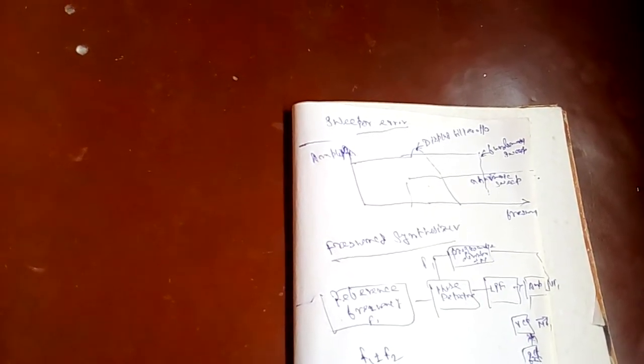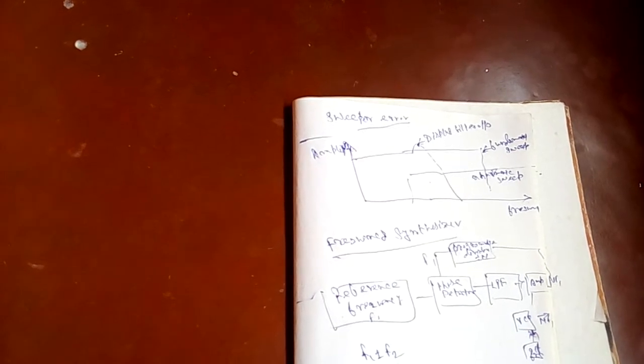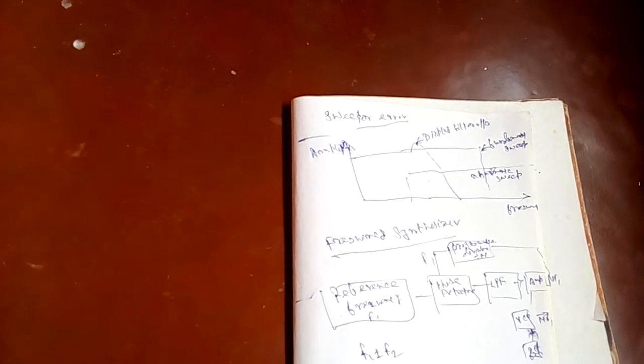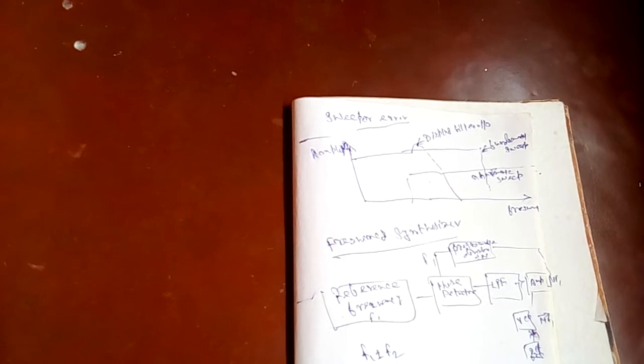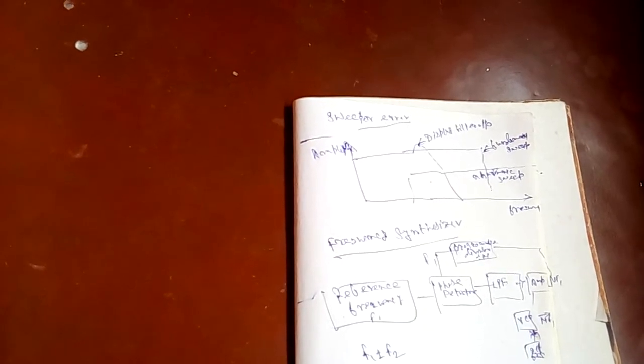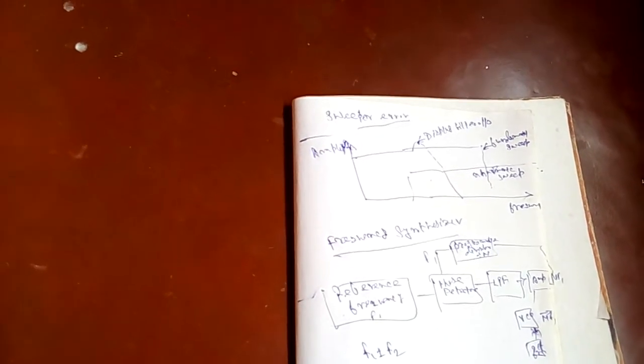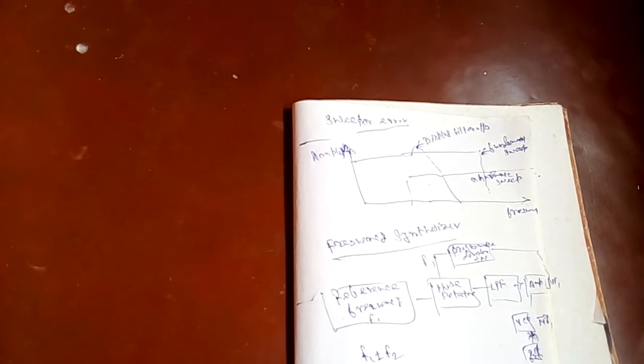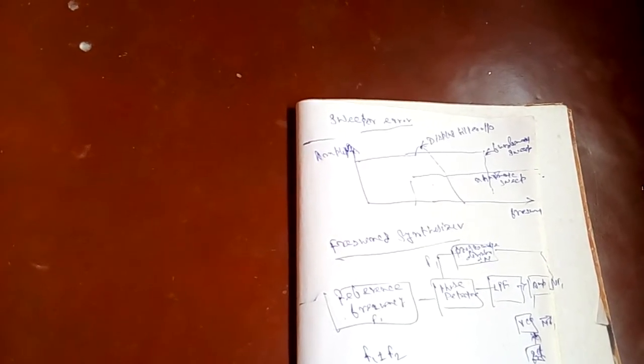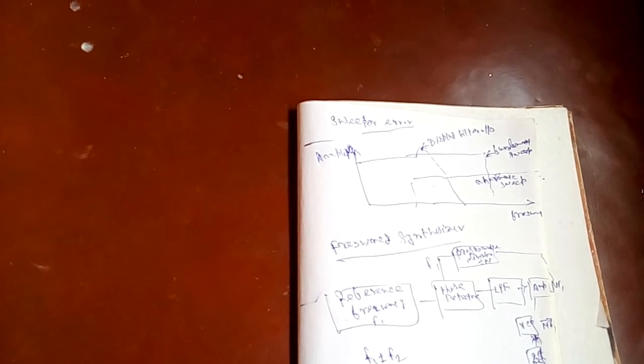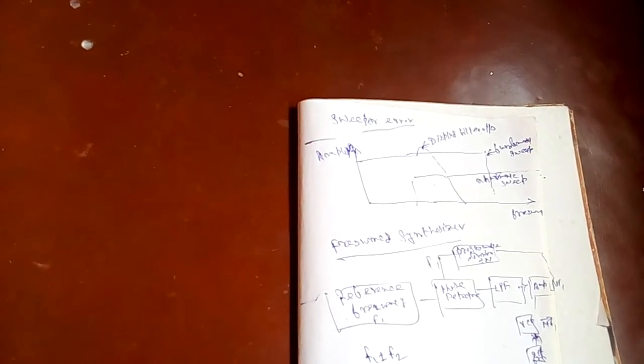and the settling time. For a large frequency difference the lock time can be long. This is minimized by presetting the VCO close to the final value, usually under microprocessor control, and letting the phase loop pull it to the exact value. The settling time is measured for the output to reach within a given tolerance of the final output.